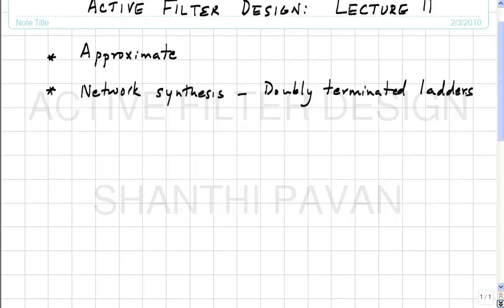That is, express this as N of s by D of s. Find a ratio of polynomials of even degree which approximates this magnitude. Then you go and factor it, and then you get the ratio of polynomials in S, where the magnitude approximates the band pass response rather than the low pass response.